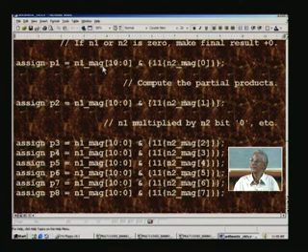This can be easily evaluated by merely ANDing each of these bits, which is concatenated. For example, we have taken the n2 LSB alone, and we are replicating it 11 times. I mean it is not duplicate, so we are repeating it 11 times totally, and each of these bits is ANDed with each of the bits of the n1 number. So naturally, if you AND, even if there is a 0 at any point, that particular bit will be forced to 0. So that is how you get 0.